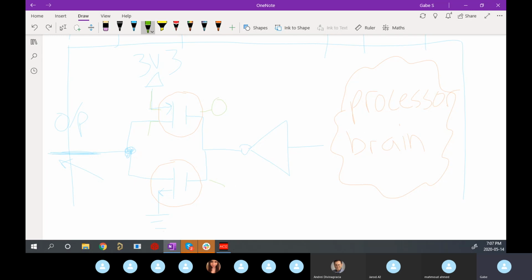Same thing on this side. I have a little input. I could press this button or send it a signal, and it'll close this switch. It'll connect these 2 things. So the thing we're trying to do here is use these connections, these inputs, to either connect our output pin to ground through the switch or up to 3.3 volts, which is exactly what an output does, right? That's what your push-pull will do. It'll connect it to 3.3 or to ground, right?